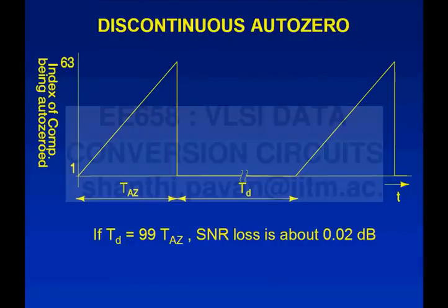The advantage of doing this rather than having substitutes and so on is that you are not doing anything hardware-wise, you are not doing anything out of the ordinary. Everything looks pretty normal, which is what you would do in a regular flash ADC anyway. You would use bubble correction to correct one bubble, and everything else remains the same.